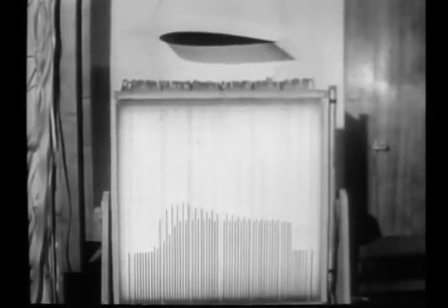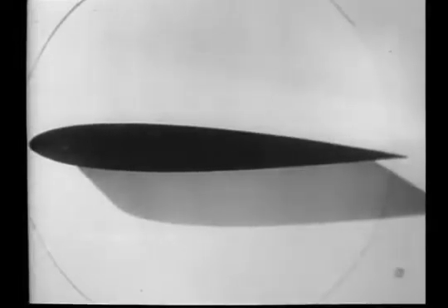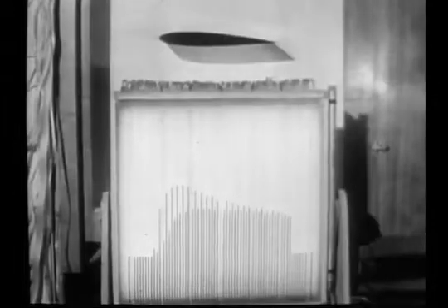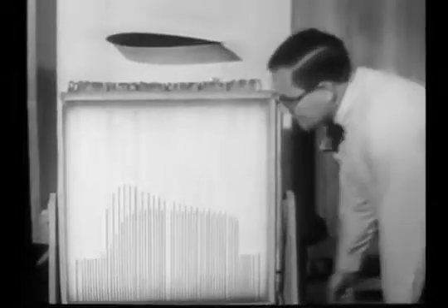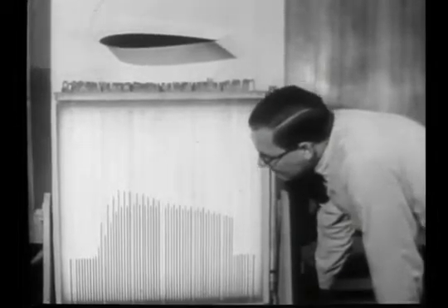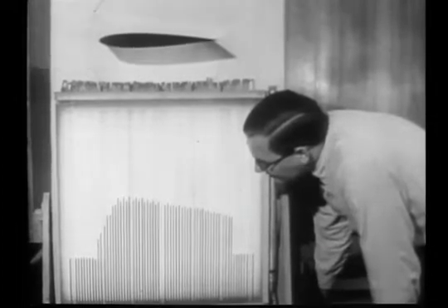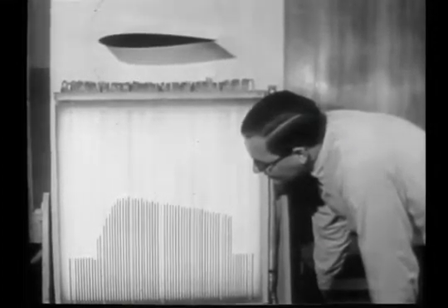Combinations of favorable and unfavorable gradients occur over the surfaces of aerodynamic shapes. This airfoil has a maximum thickness of 12% of the chord length, located about 1/4 of a chord length aft of the leading edge. The model contains pressure tubes mounted flush with the surface for the measurement of the static pressure distribution. These tubes are connected to the manometer alternately from the top and bottom surfaces. When the profile is set at 0 angle of attack, the pressure distribution produces this picture on the manometer.